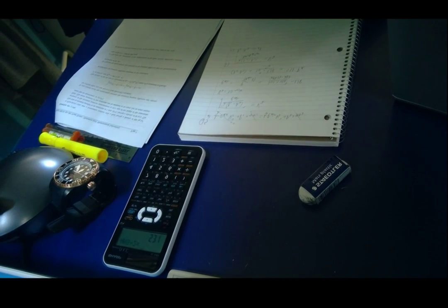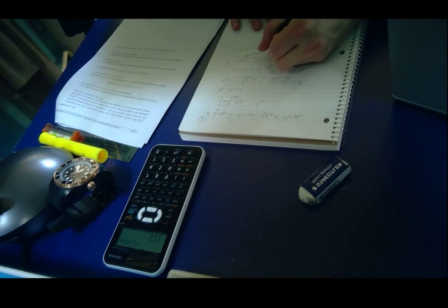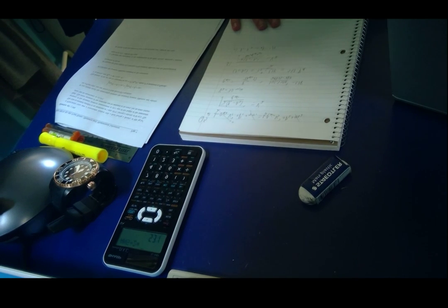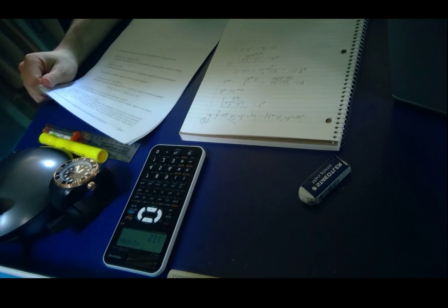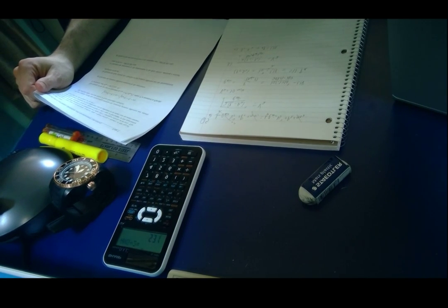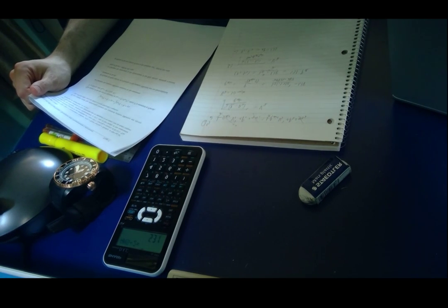So our P1 minus P2 will become delta P. Now we assume a nominal value of 30. This means that the values will be what happens at 30, so 1.18 for delta P. The dynamic pressure measurement has an accuracy given by the height of the manometer fluid. The static pressure of the airstream can be assumed to be exact, but its static temperature has an uncertainty of 1.2 degrees Celsius. It says the accuracy of the dynamic pressure measurement is 0.1 millimeters of the height of the manometer fluid.